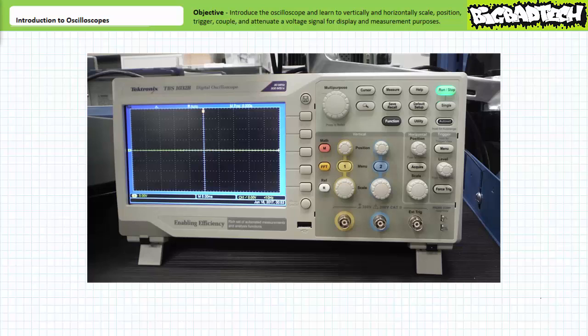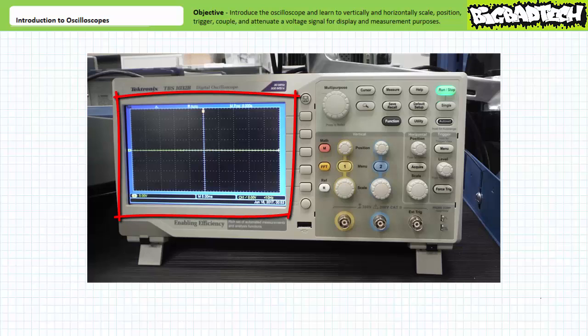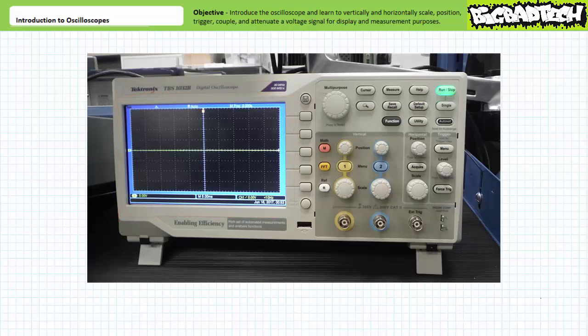Bottom line up front, an oscope is exactly like a voltmeter, only it displays a picture of voltage. An oscope takes repetitive samples of voltage, then draws the result on a display that one can zoom in or out on, shift up or down, left or right, and with pretty minimum effort perform some basic measurement, comparison, or mathematical operations on. The oscope is a powerful, sophisticated tool.